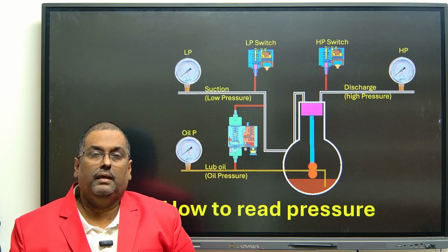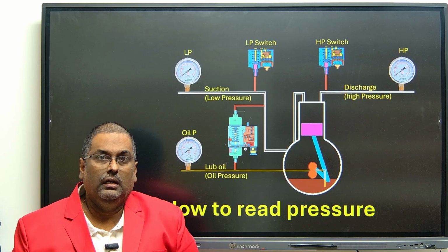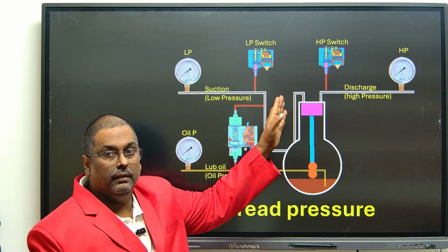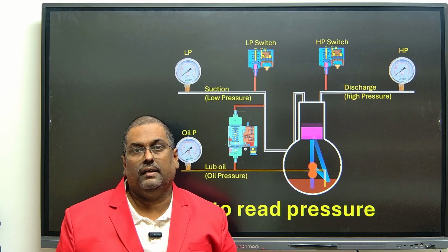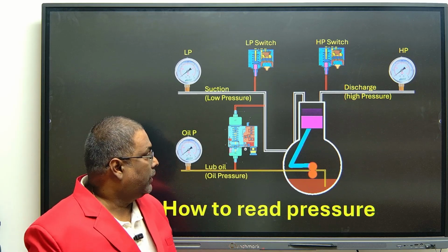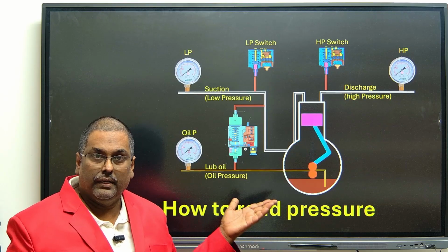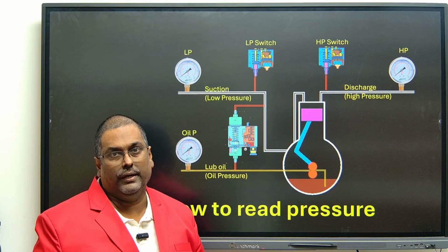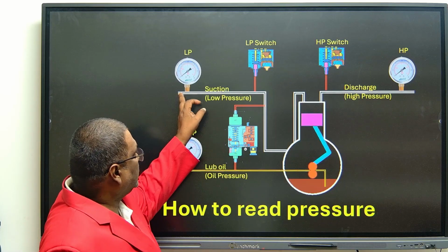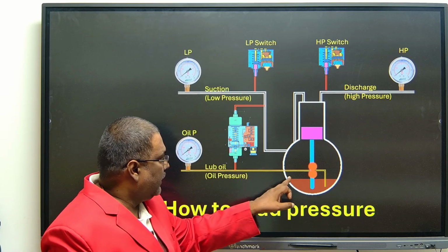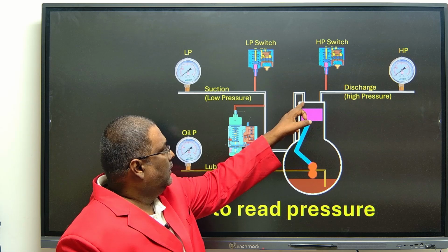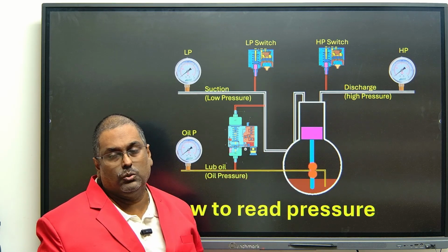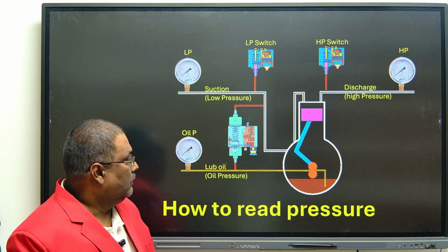By any means, if there is a problem with the expansion valve and some liquid comes back, it will get evaporated here and then go, so liquid will not be injected directly to the top of the piston. I mention this in the chapter on reading the pressure because there is a point there. So the suction pressure comes to the crankcase, and from the crankcase to the top of the piston through the suction valve, and the discharge valve goes out as usual, like a normal air compressor.